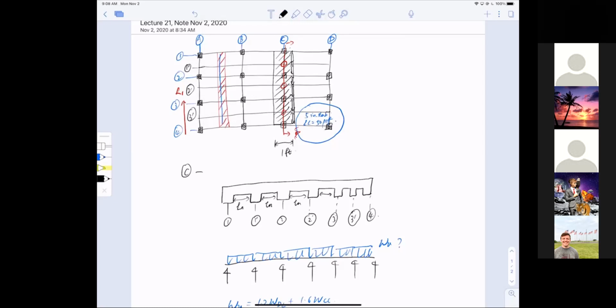It's just a giant slab. Why do you just pick 1 foot? Because when we design it, we only take 1 foot per design, and the reinforcement takes care of this foot. The spacing between reinforcement is going to take care of every individual strip. So when you design it, you only need to design 1 foot of strip sitting on top of these. Okay, so that is known.